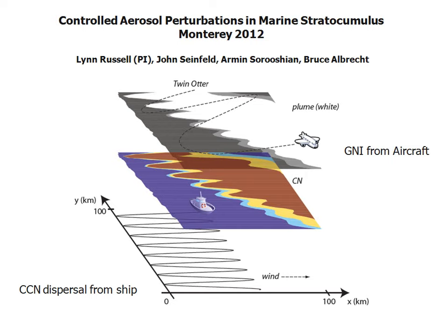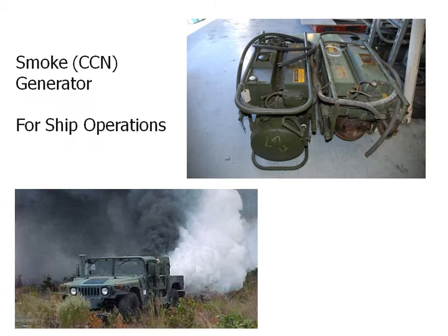In addition, on that aircraft, we've also developed and tested a technique for putting out radar chaff. The chaff is cut to three-quarters of a millimeter, so it has very slow fall velocity, but it's optimized to be seen very well with a 3-millimeter radar. It's a quarter wavelength. We will use this basically as markers. Sometimes it's hard to figure out where we really put down these lines, but we can use this as a marker that can then be detected by the radar.